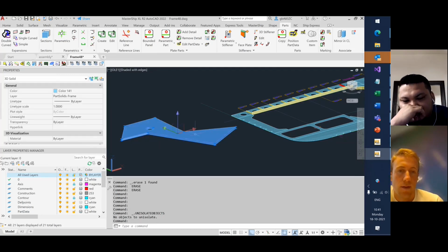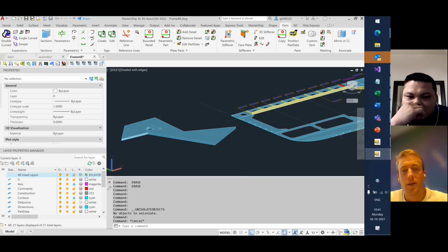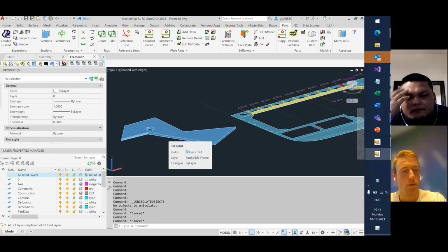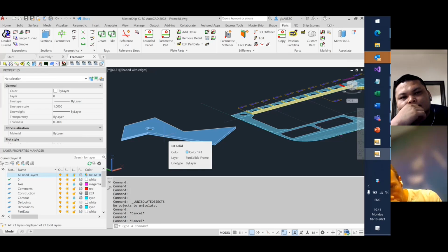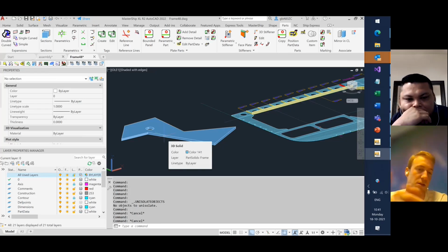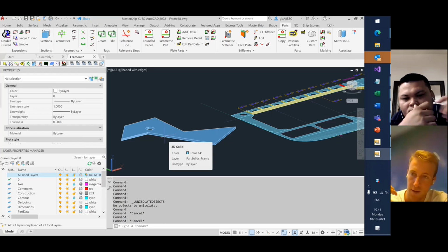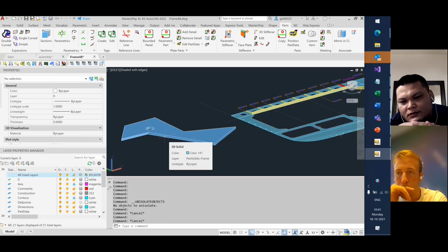If you do solid to part, it actually becomes a construction element. You can only do this for flat solids. You cannot do it for curved solids. And there is also really no purpose in doing it for curved solids, since then you have to make an expansion first anyway.